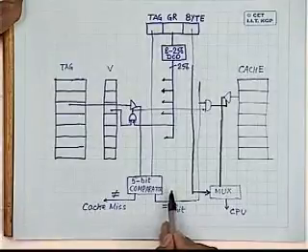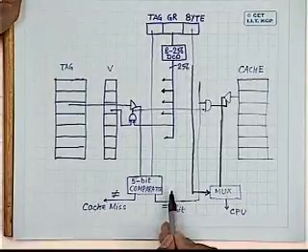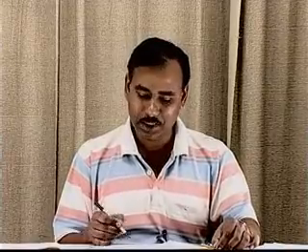See, in case of cache memory, what we are trying to do is we are trying to make the operation very fast. So having just one more comparator may not be that costly, but the time may be costly. Okay, but that is feasible. It is not that what you are saying is impossible. That is also feasible. But having just one more comparator or 2 more comparators may not be that costly when you go for VLSI implementation.